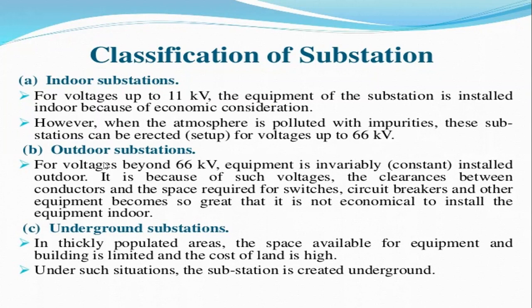Next one is the outdoor substations. For voltages beyond 66 kilovolts, equipment is installed outdoors only. It is because of such voltages, the clearance between the conductors and the space requirements for the switches, circuit breakers and other equipment. For above 66 kilovolts, the equipment is installed only outdoors.